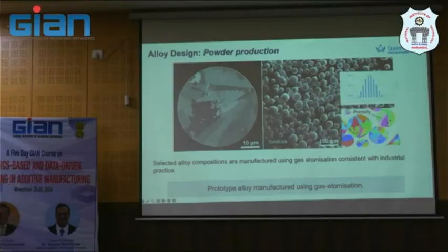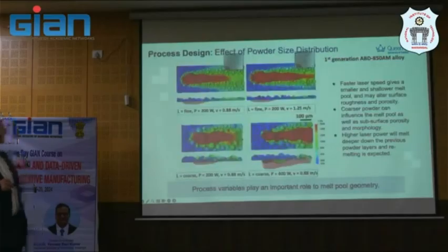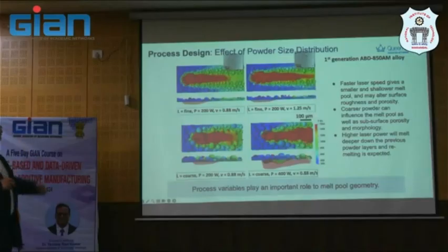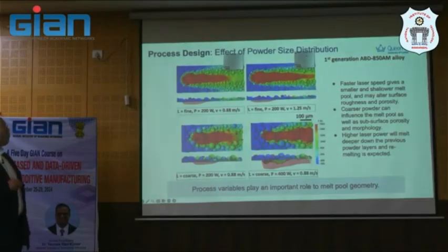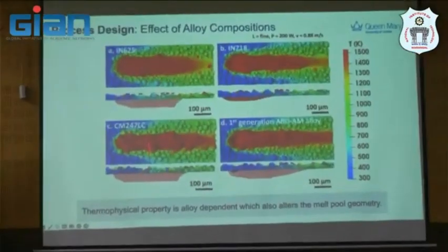And at that time, we already knew the hurdles for this processing. You have trapped porosity, microstructure, even dendrites, something like this. And then we ran simple tests. At that time it was not very fancy, but it gave enough information for us to know the importance of the processability parameters for the new alloy that we are going to develop, in terms of porosity that may lead to cracks or surface morphology at different conditions compared with traditional alloy.